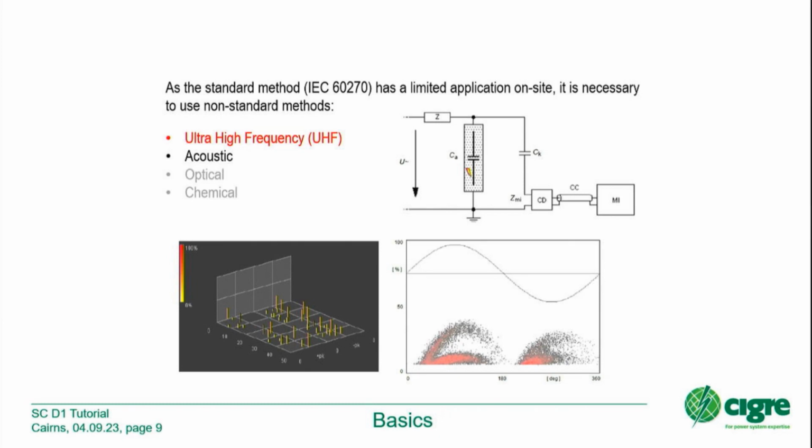So then I was thinking either the GIS equipment is too good or the test is not difficult enough. But the reality is that we don't have any PD on all the new equipment. As end users, we prefer to put some effort and time on monitoring of gas rather than on the UHF. Nevertheless, we require those UHF sensors that we use during maintenance. Each time we commission a switchgear, we ask to do the UHF method at operating voltage, so we can compare later during the next maintenance steps, and then select the bay most subject to PD and start maintenance on that one, as we know the others have less activity. Is that a good way to proceed?